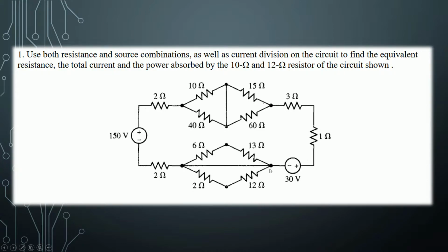It is a short circuit because it is directly connected to this node right here. What this tells us is that the current will just pass this circuit and it will not go through these resistors because, well, this has less resistance, so the current will just pass right here, but we'll get into that later.